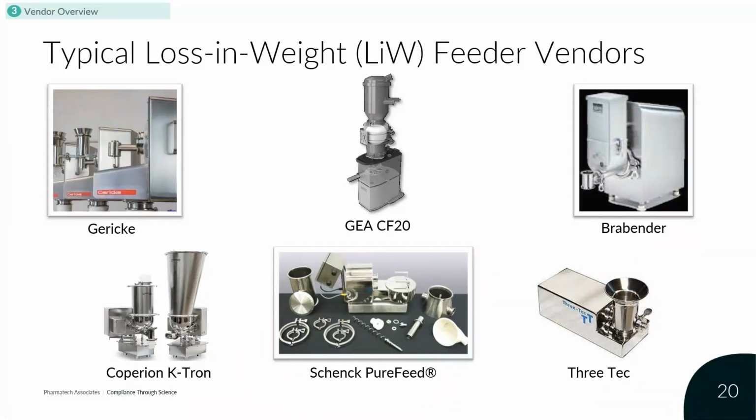Beside that, of course, some of them have very different load cell technologies, which have an impact on the precision of the feeding. Also, the control algorithms and the control strategies around the feeder are very important to discover.